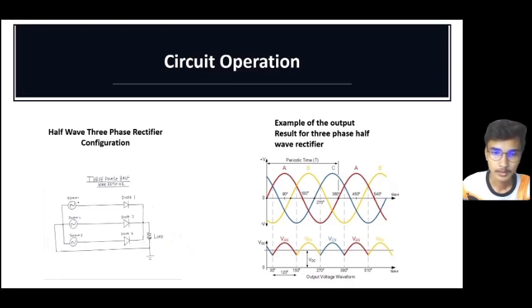From the research that has been made, only one diode can conduct the voltage at a time. The diode with the largest instantaneous voltage value will only work in forward bias, while the other diodes will be under reverse bias condition.